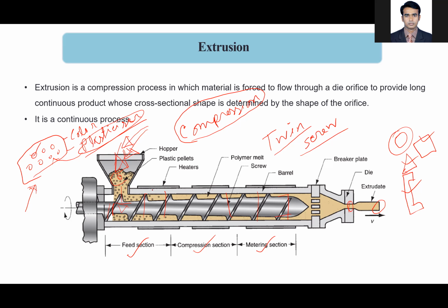There is a provision for vacuum applied in here to get those air out of this system. And if the diameter of the screw is constant, there is no chance that the air will get out. Then the plastic will be full of voids. If we look at the final product, you will get air voids in the final product. This is one of the reasons, to remove the air or gases from the melt.